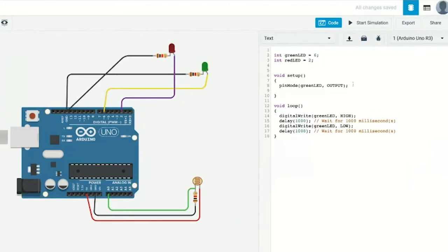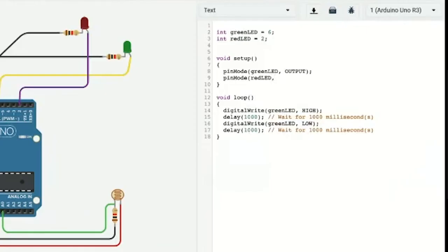Now we're going to have to get inside of the void setup function, and we're going to have to connect the pin using the pinMode command. Simply call the command by typing pinMode. Watch your capitalization on the second word. Then use a bracket and pass it the variable that you have assigned to indicate the red pin. Pass the pinMode function the second parameter, setting it up as an output. Use a close bracket and a semicolon to terminate the line.